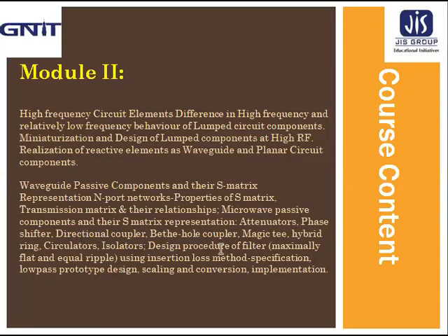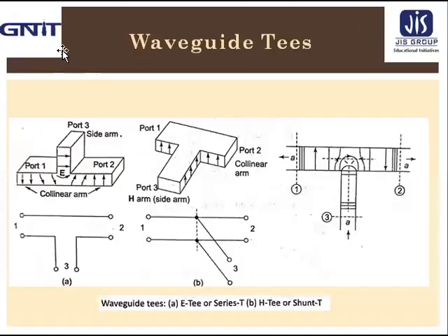Now, today we will discuss about magic T, that is a microwave passive component, and also we will discuss the S matrix representation of this magic T. For that, first we have to know what waveguide T's are. Waveguide T's are three-port components.